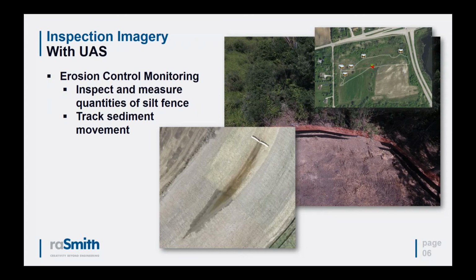There was almost 10,000 linear feet of silt fence installed on this site. And all that silt fence had to be inspected, at least once a week, and that's usually either by default once a week or after a significant rain event. And this site being quite large, some of the fence is easy to get to in terms of inspecting it, and other parts of it are not, especially after it had rained and everything was starting to be graded, and it gets very muddy and messy.